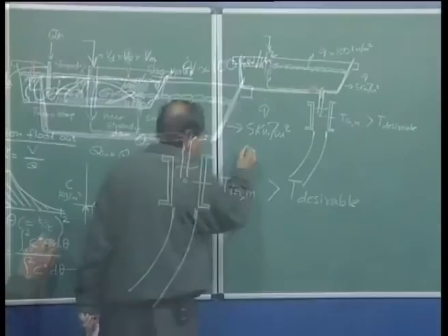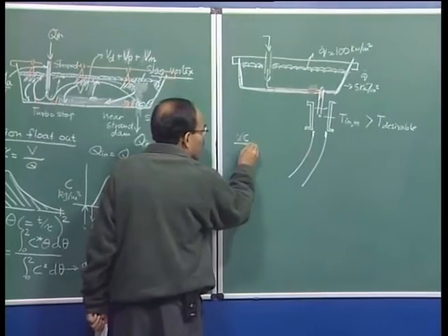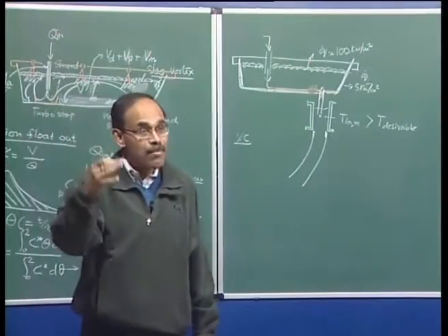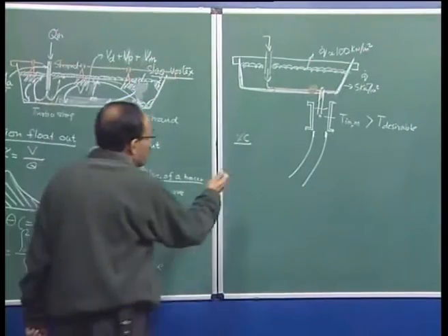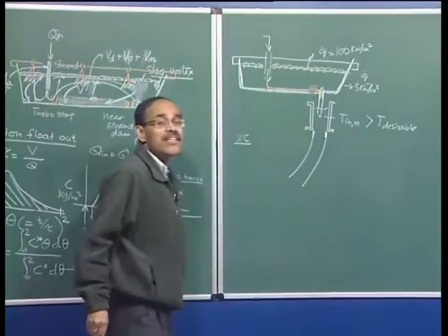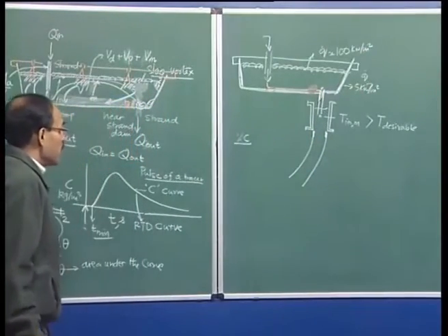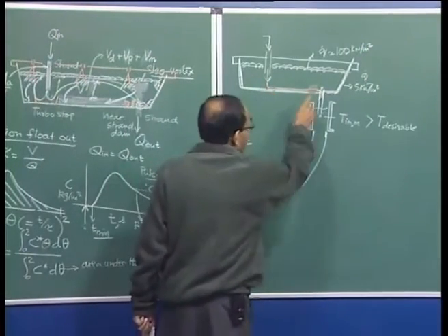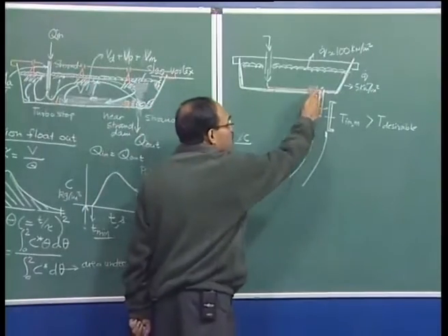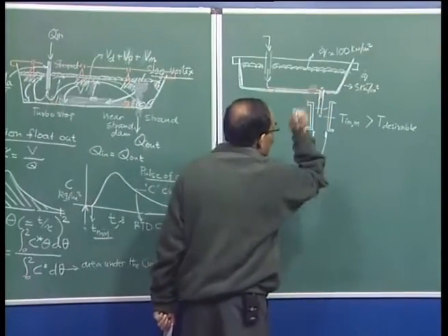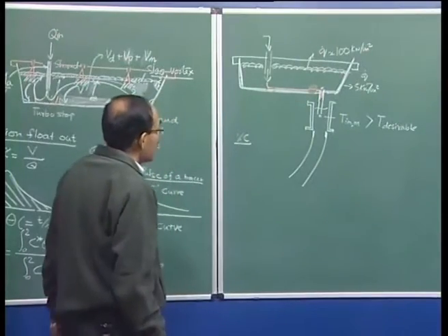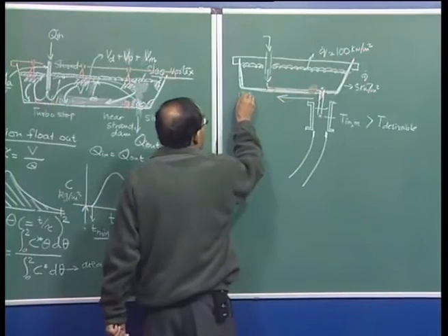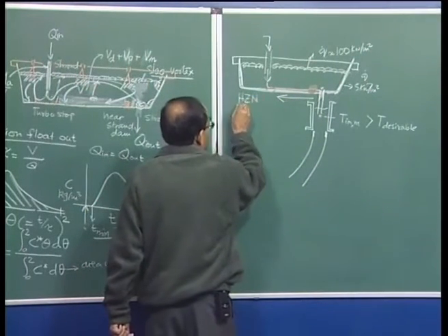If the steel has a melting temperature which is a function of carbon and other composition, the temperature over and above the liquidus temperature is termed the extent of superheat. So, we are talking about a desirable superheat here in the range of 15 degrees to 20 degrees, that is perhaps ideal. Now, if you have too large a temperature here, and we do not want any premature solidification, how is it possible for us to deliver molten metal into the mold correctly? So, we can have in between the two what is known as hollow jet nozzle technology. This is a patented technology actually.